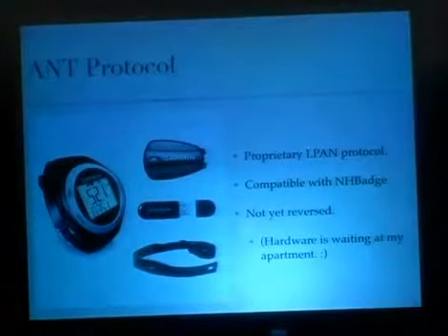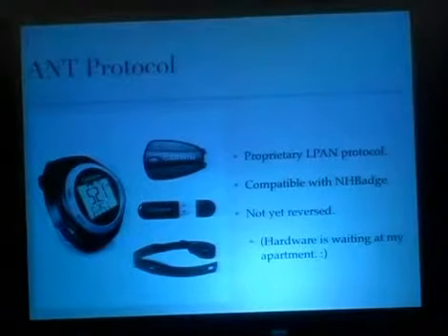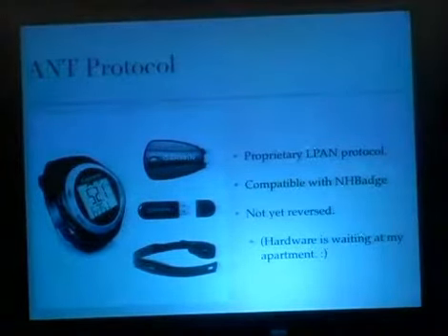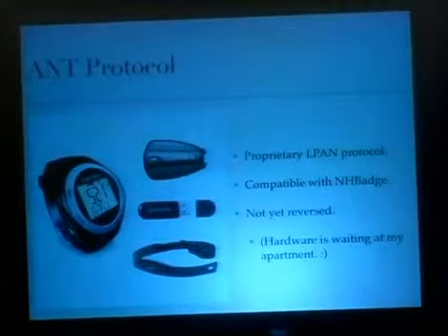This protocol is open at the higher layers. All of the application layer stuff, all of that is open. You can get it free of any NDA. There's tons of example code. The only thing proprietary here is the link layer. The PHY layer is easy enough to figure out. Like most everything, it's a Nordic RF chip running at 1 megabit per second.